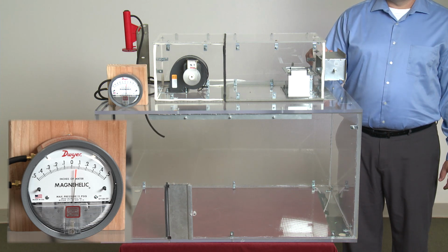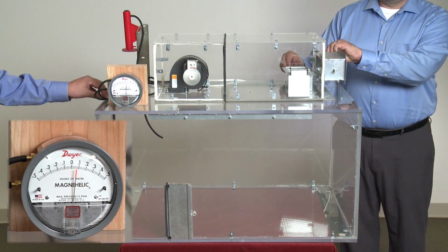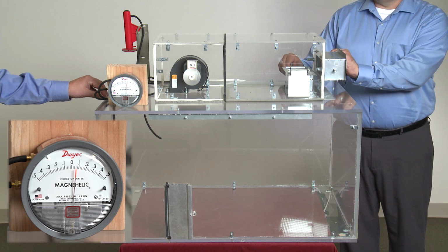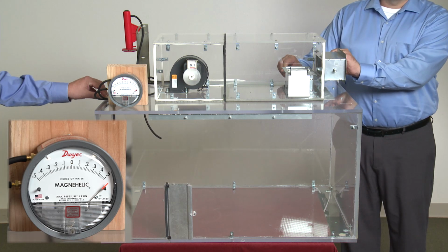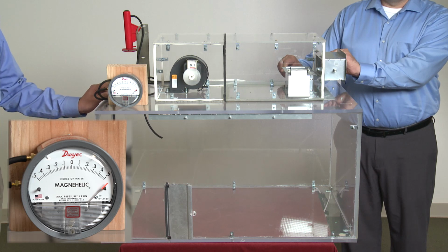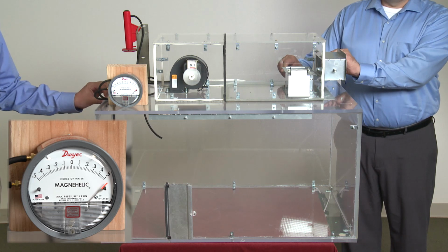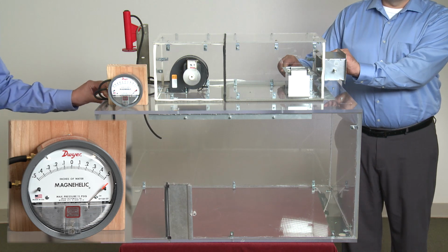Next, let's see what happens on a mild day when airside economizing. I'm going to have Eric modulate the outdoor damper to fully open and the return damper fully closed. And you see that the needle pegs. Building pressure is overly positive. The air handler is trying to bring in 100% outdoor air for economizing, but the building is not leaking enough to relieve all that air, so building pressure rises dramatically.